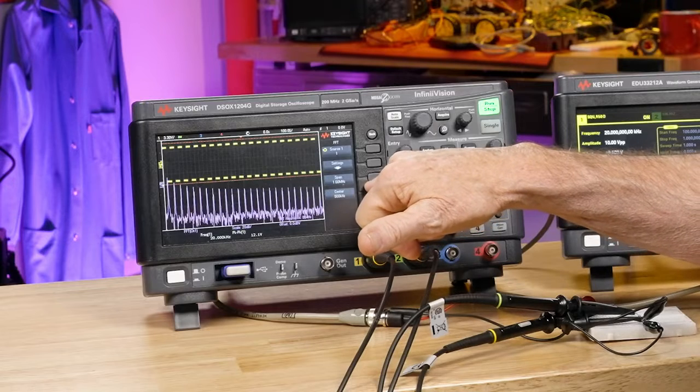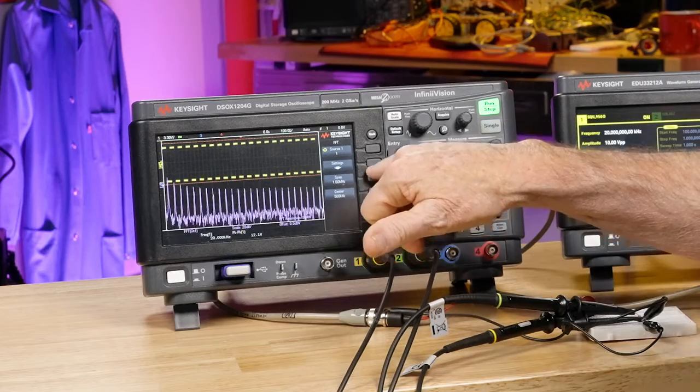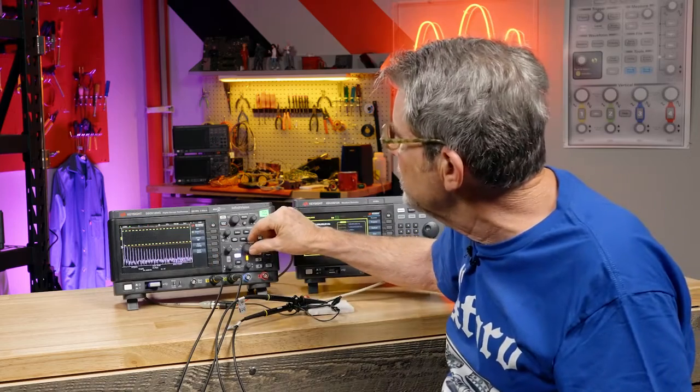If you wanted it in frequency per division, just divide that by 10. So we're basically 100 kilohertz per division. And then we have the center set at 500 megahertz. Now we can make measurements on this signal as well.